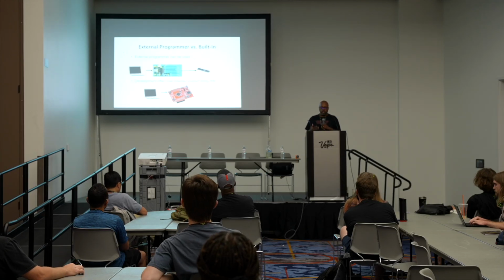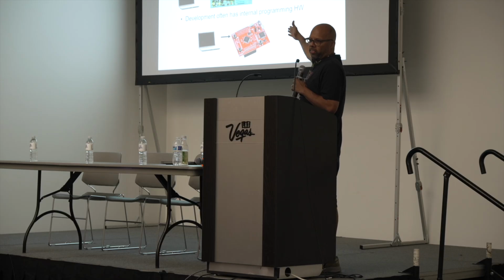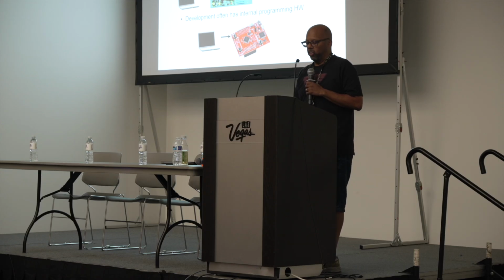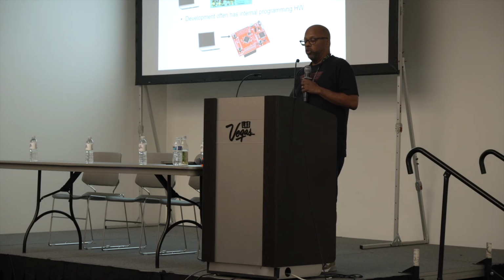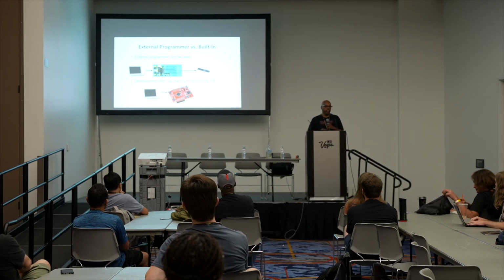So how do you program one of these things? You write your code on some development environment like a laptop, and eventually you have to put it onto the microcontroller. Either you do it with some programmer like that one, a programmer device connected by USB to your development machine, and then you put the chip in there and connect it to that. This is a really old-fashioned one, but same idea. And in fact that's how it's really done in products, because the other way is like this, which is much more common if you're going to do it yourself.